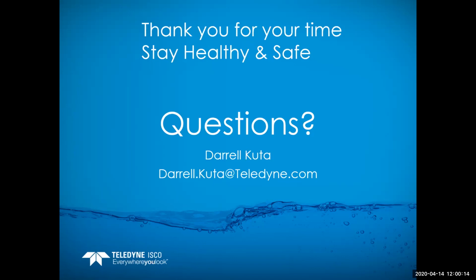Another question came in is, which non-contact sensor is best for level measurement in a tank: ultrasonic, laser, microwave, radar? So as far as tank monitoring, the ultrasonics and the radars are the most common ones that I see. I don't have any experience with the microwave. Well, I guess that would be the radar.